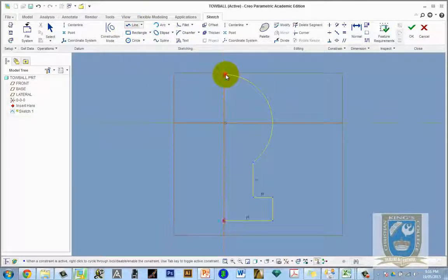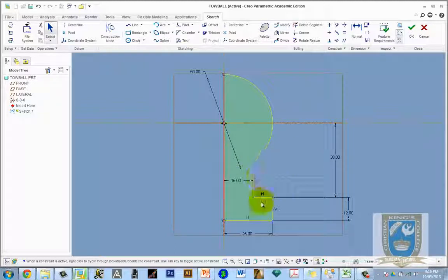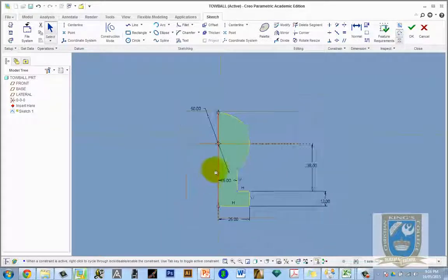So use my line tool, I click once, I click twice, and if I now go arrow, this should fill in, which it does. There's no red dots. There's shaded, which indicates that it's a closed sketch. And also always click on your overlapping geometry to make sure there's no purple lines appearing, means you haven't drawn a line over top of a line. Now you're almost ready to revolve it.